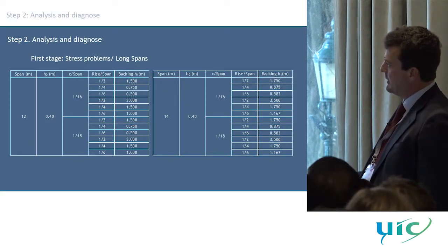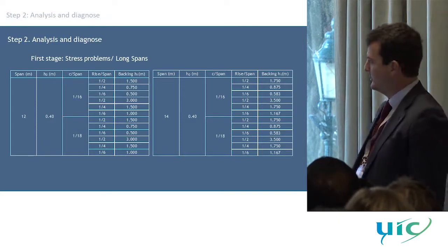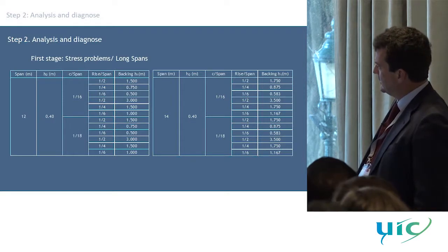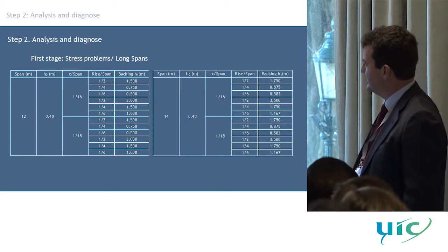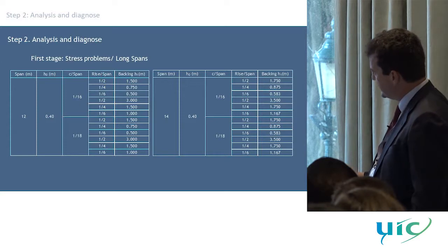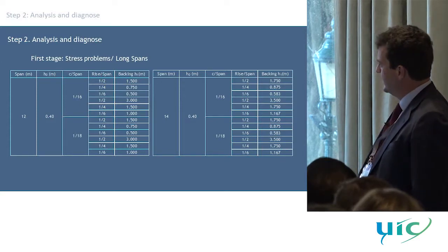So we established in the models, we did some 2D models and 3D models. We established some masonry section controls in order to compare one case with another: reactions, of course, stresses on the infill, vertical and horizontal, crown and rigid. Also, we established this vertical section in order to know more or less which earth pressure we were mobilizing in that sense.